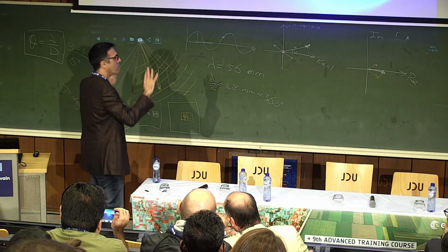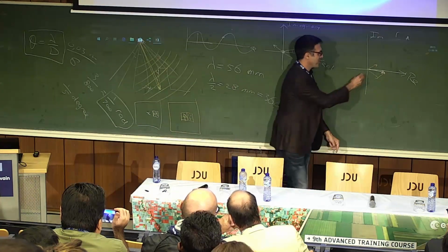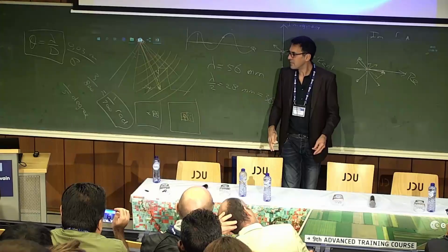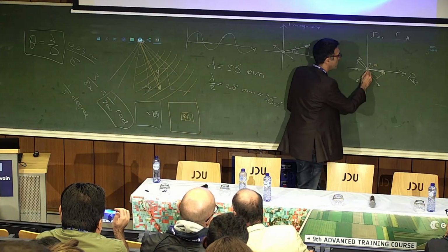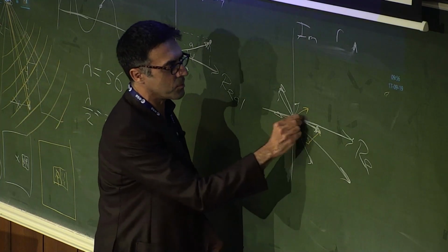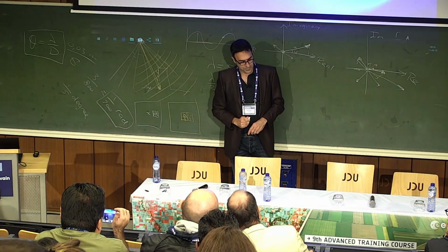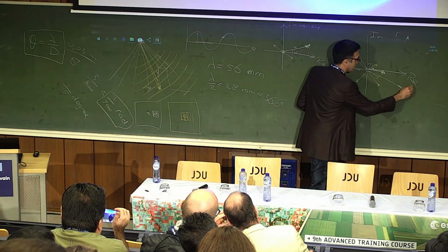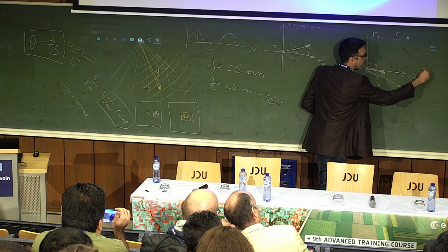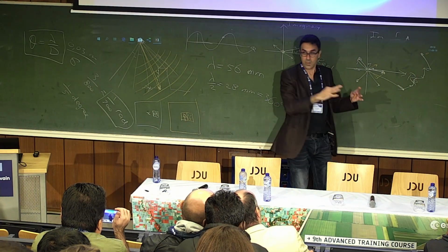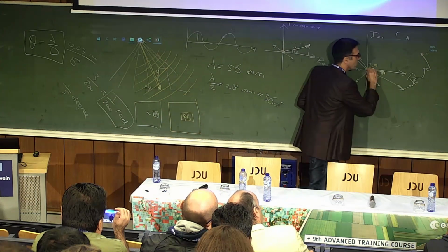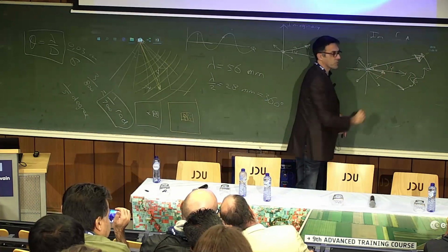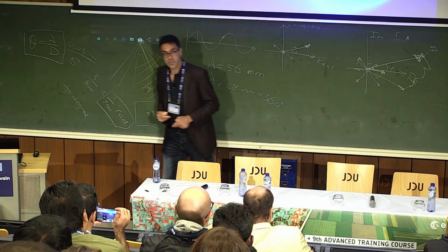So we're getting a whole load of little vectors and big vectors, all these things together. And maybe there's one big object here, maybe the board, which has a large amplitude, and the glass is a small amplitude, and all this stuff is getting together. So what I'm going to get for this particular pixel is the coherent summation of all these vectors, right? I can add them all up. And in the end, all the reflections from this classroom together will be one resultant vector, which has one amplitude and one particular phase. That is going to be in my file, and that is what Magdalena is going to show you in the afternoon.